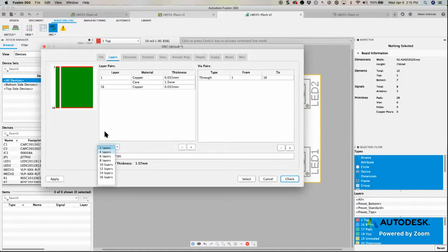So for that reason, you won't really ever see numbered layers. But as you can see, if you need 3, you might as well go with 4. Exactly. Actually, if you send a 3-layer board to a board house, they're maybe going to say no, or they'll actually make it a 4-layer board anyway. It's just they won't do anything on one of the layers. It's quite possible. That's what'll happen.